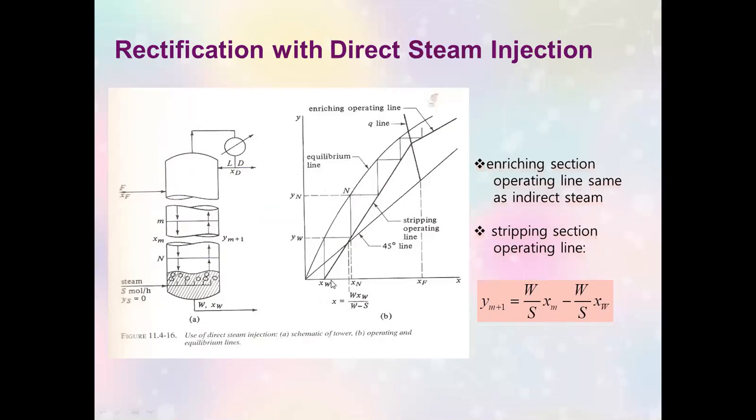the graphical approach of determining the theoretical number of stages, the stripping section operating line, this line here below your column, should have been drawn right on the y equal to x line, or the 45-degree line. In this case, it's not drawn right on the projected value of the mole fraction of the bottom's liquid on the 45-degree line, but it's right on the horizontal axis.